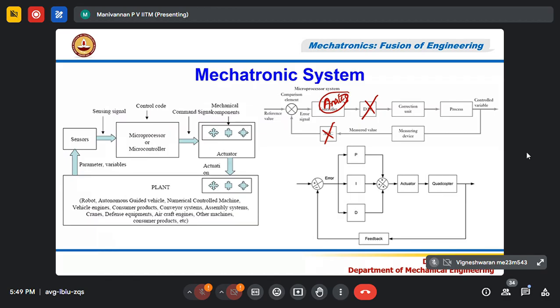Similarly, if I have a digital controller, I can put in any control software. The same ECU will work for controlling the engine. Instead of that program, you put, for example, steering control software, and it can control the steering system. Instead, I put ABS software, and it can control the ABS system. That is the advantage. Changing the same hardware to make it different is very simple: delete the program and put the new program over.